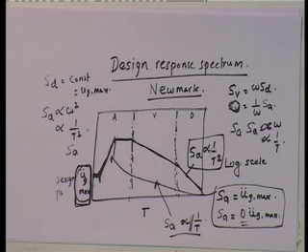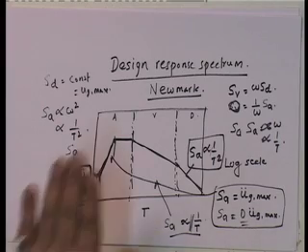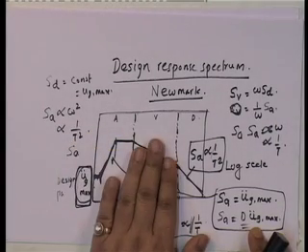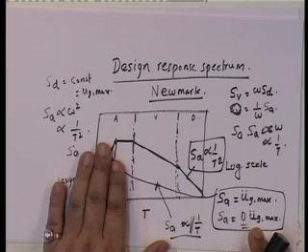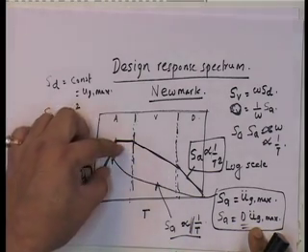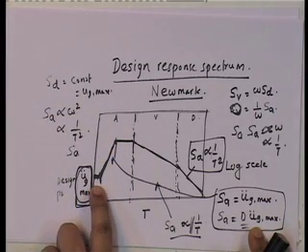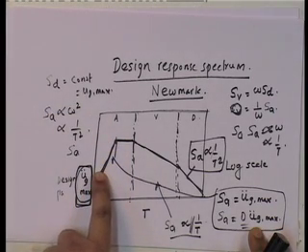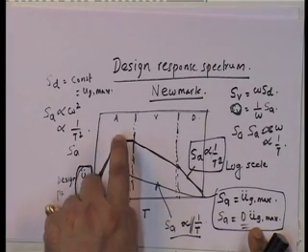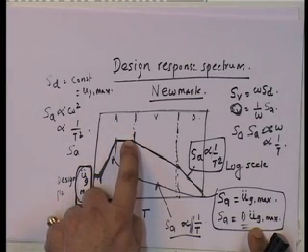Okay? And Newmark actually developed a specific way of determining these from past earthquakes. Okay? So, in a sense the point still remains that you have an acceleration controlled zone, a velocity controlled zone. In the acceleration controlled zone, S A is a constant for all practical purposes excepting for a transition zone, because you need to go from peak ground acceleration to some number of times peak ground acceleration.